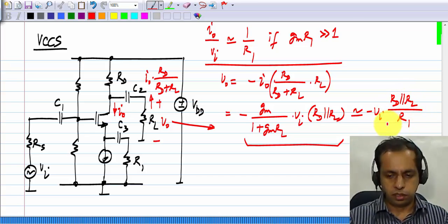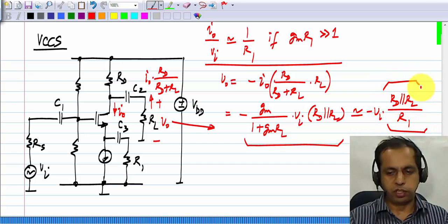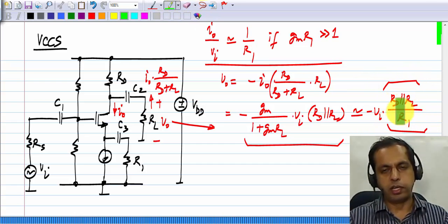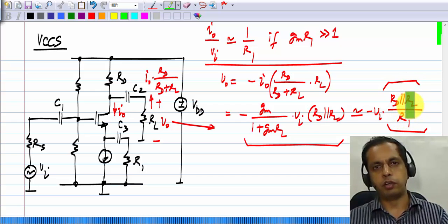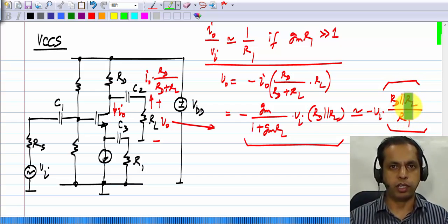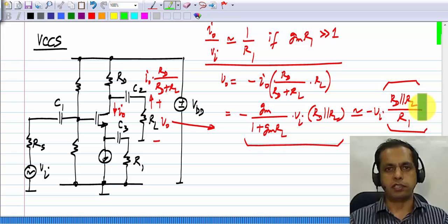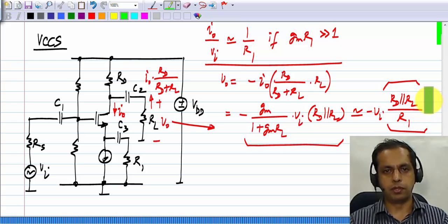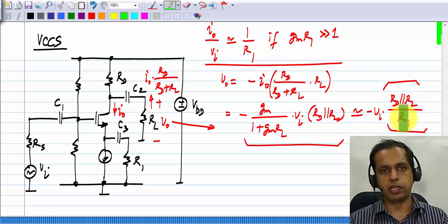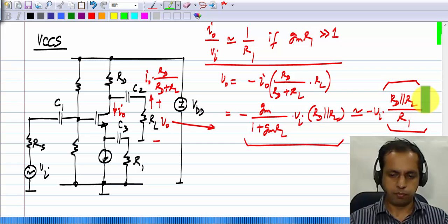Okay, so the gain, the voltage gain, if you think of it that way, is defined by a ratio of resistors, and that can be defined accurately. That is more accurately than defining the transconductance of a MOS transistor, which varies significantly with temperature and so on. Okay, especially on an IC, the ratio of resistors can be quite accurately fixed.